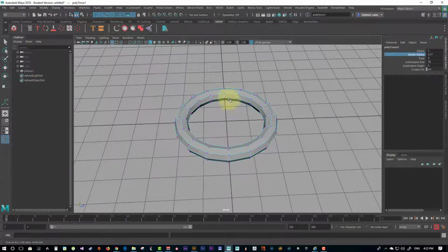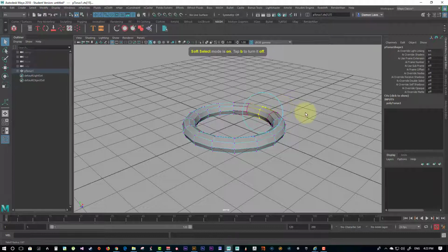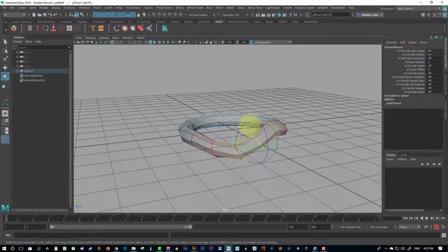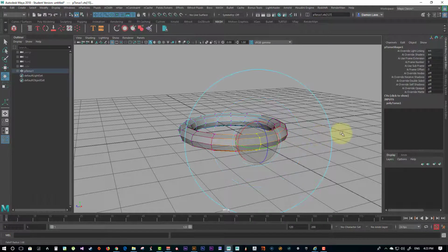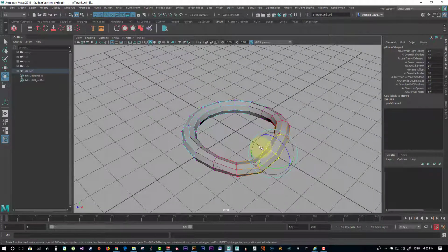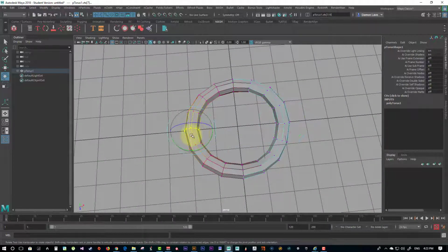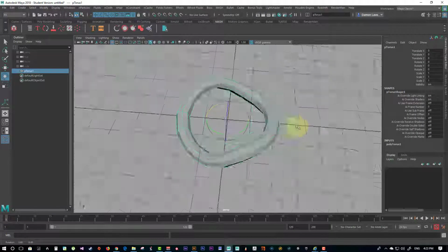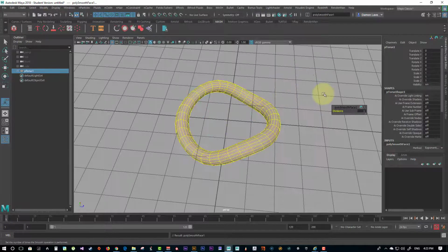Alright, I'm going to change the mesh a bit, so I'm going to press B and make it so I'm almost catching everything, like the distribution of the weight is going all the way until the middle, but not all the way there. And I'm just going to bend it like so, about 15 degrees, maybe a little less. Maybe we should make this bigger. Let's make that a little bigger anyway, like so. Yeah, something like that, and then we'll grab this and go the opposite direction. So we got this bent thing, and now I can smooth it out, like that.